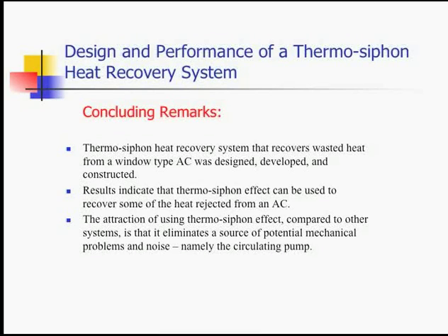These are some concluding remarks. We have seen that a thermosyphon recovery system that recovers wasted heat from a window air conditioner can be designed, developed, and constructed. Results indicate that the thermosyphon effect can be used to recover some of the heat rejected from the air conditioning. And this method is very attractive because we don't use a pump, to avoid some mechanical problems and noise.